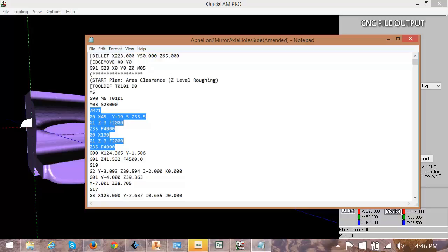Get all this right, make sure it is precise and absolutely correct, and then you can just copy and paste this particular module of code into your next file if you want to make one, and all you need to do is change the various distances from canister housing to axles, and from front axle and rear axle to the rear of the block. Okay, does that make sense? So this bit of code tells the machine to drill the axle holes. It's not normally there.